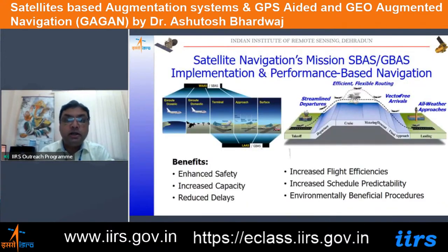So this is again how we are benefiting from the WAAS system. So we have a takeoff of the aircraft, and another advantage is that if we are using the SBAS based systems, we need not be connected with the DME or the VOR systems on the ground, and that enables us to fly point-to-point also.